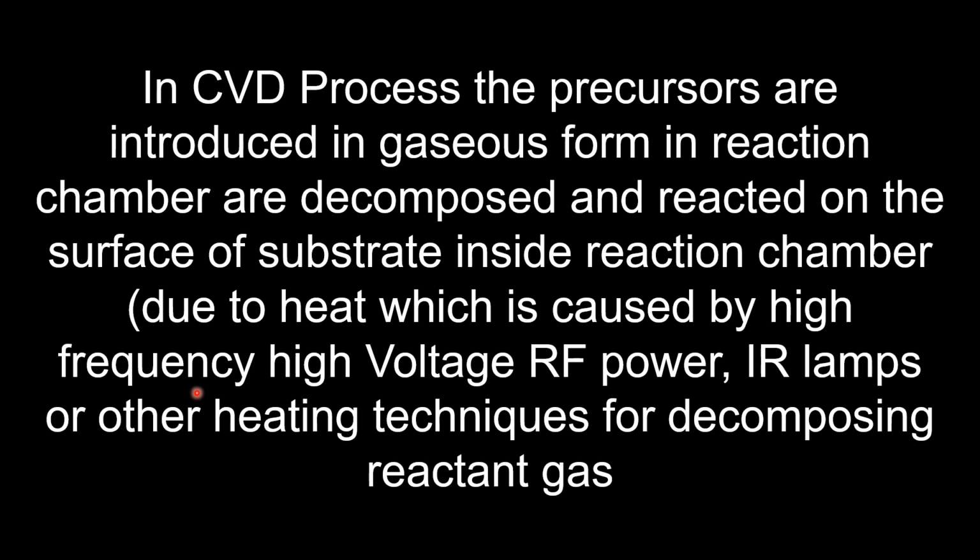Student, please note that in the chemical vapor deposition process, the precursor materials are introduced in a gaseous form in the reaction chamber, and are decomposed and reacted on the surface of the substrate inside the reaction chamber due to heat, which is caused by a high frequency voltage, IR lamp or other heating technique for decomposing the reactant gases.